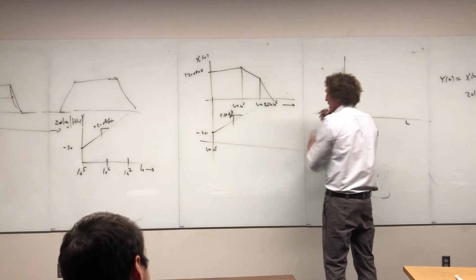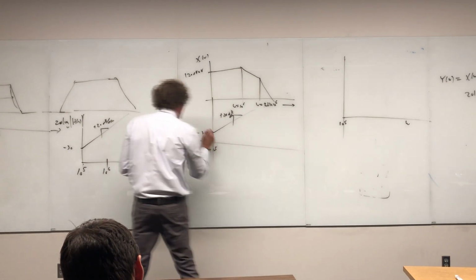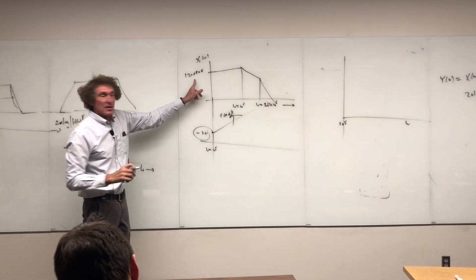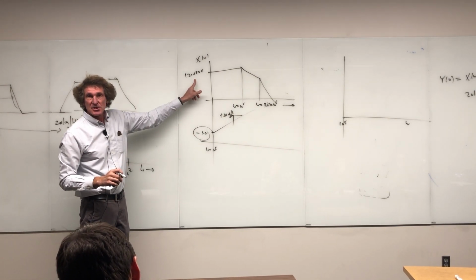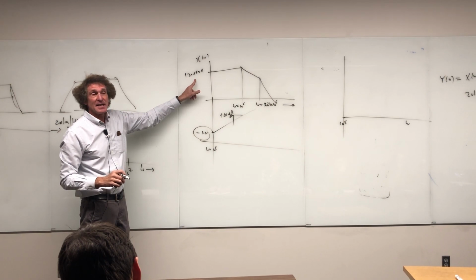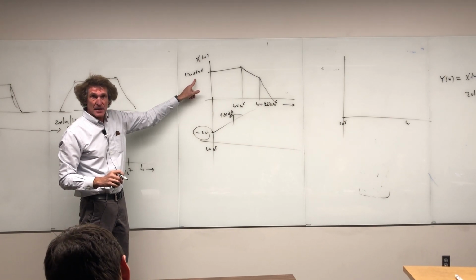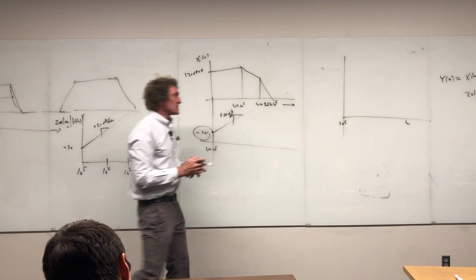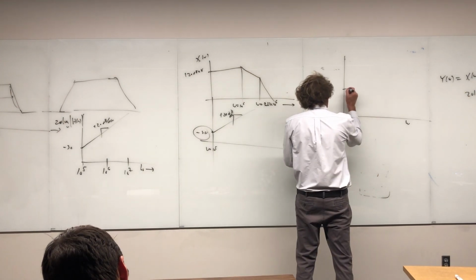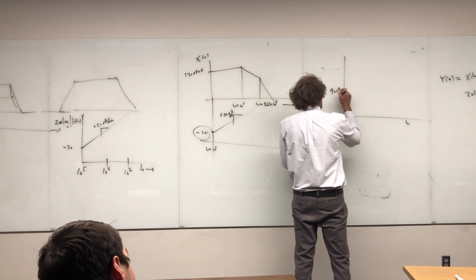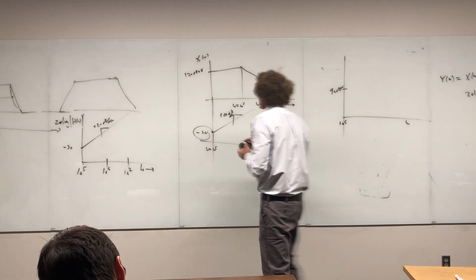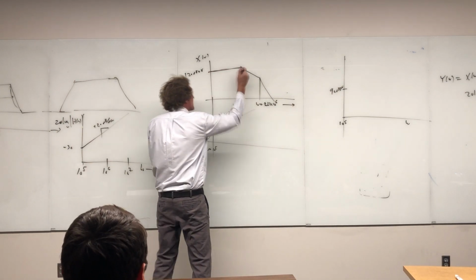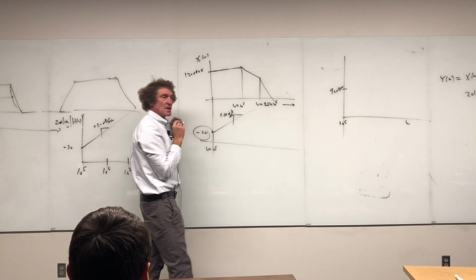I come up and take a look at this. I've got minus 30 that I'm going to add to 120. Does everybody see that? So that's going to be 90 dB microvolts. Correct, class? So it comes in at 90 dB microvolts.